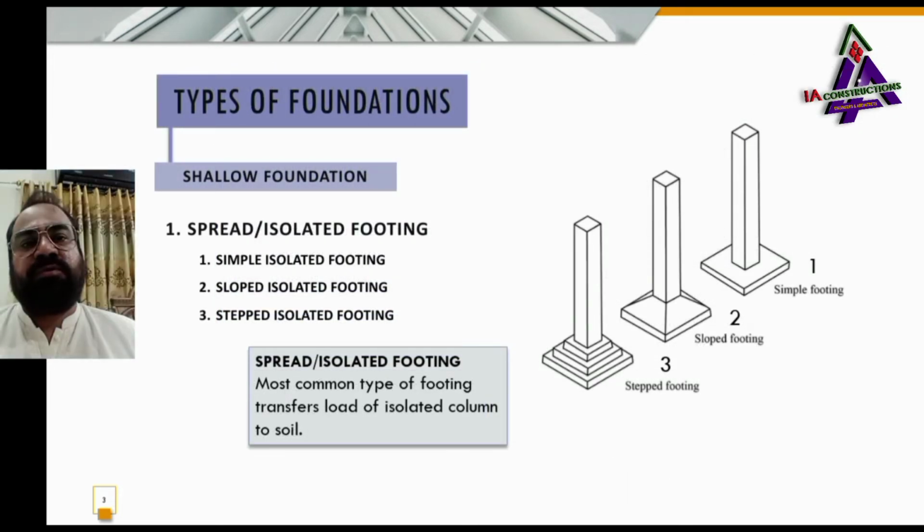Guys, spread or isolated footing is the most common type of footing transfer load of isolated column to the soil. That's why it is also called isolated footing. Guys, spread or isolated footing is mostly used in foundations of houses and small buildings. It have further 3 types as you can see in the diagram.